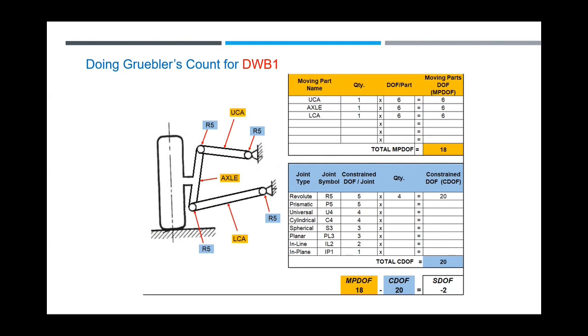All right, so in a regular wishbone suspension, the tire here is basically a parallelogram, right? And even though they call it 4-bar, it's actually 3 bars that are moving, right? So that's what the calculator just cares about. So if I made a mock-up of what's on the screen here without the tire, this is all 5 revolute joints, but you notice they're not parallel with each other.